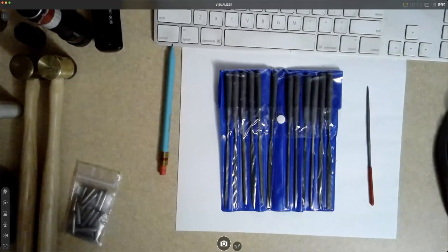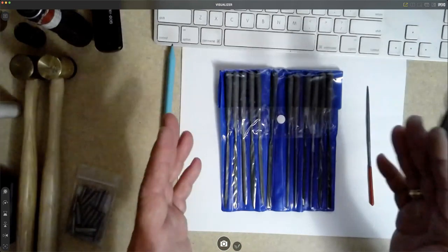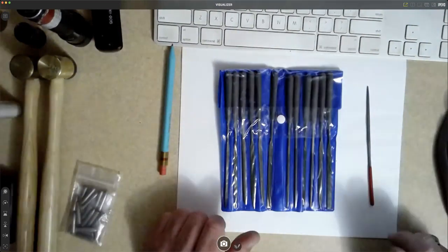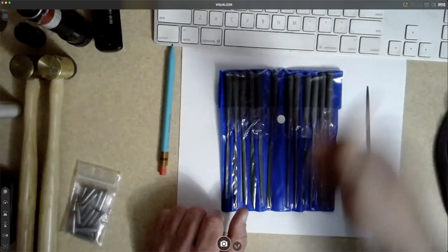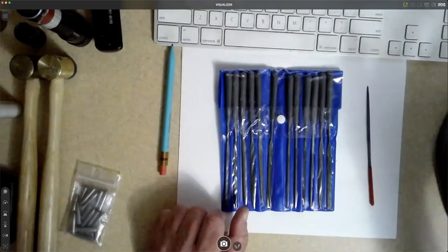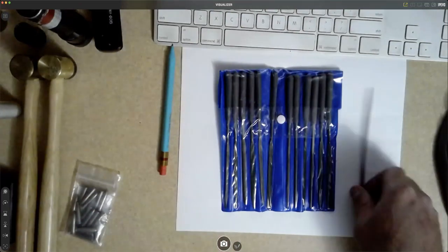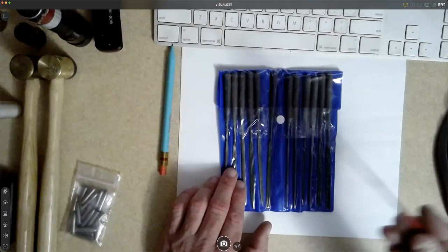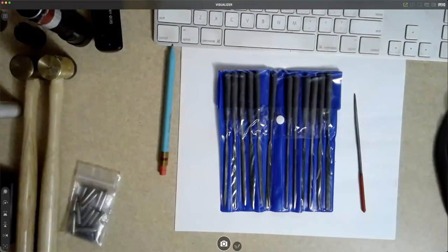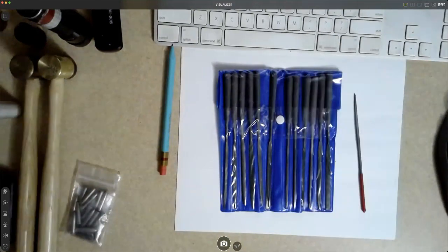Harbor Freight sells a block of what looks like gum rubber, like a big eraser, basically. That's used to clean up or redress a sanding belt. So if you're using a belt sander and it's not sanding, you take this block of rubber and just hold it up against the belt, and it takes all of the dust buildup straight out. That also works on your files, again only one direction, and that'll help pull it out. On the bigger files, wire brushes work really well to get that stuff out. I'm talking about the hand-used wire brushes, not the drill-powered wire brushes.